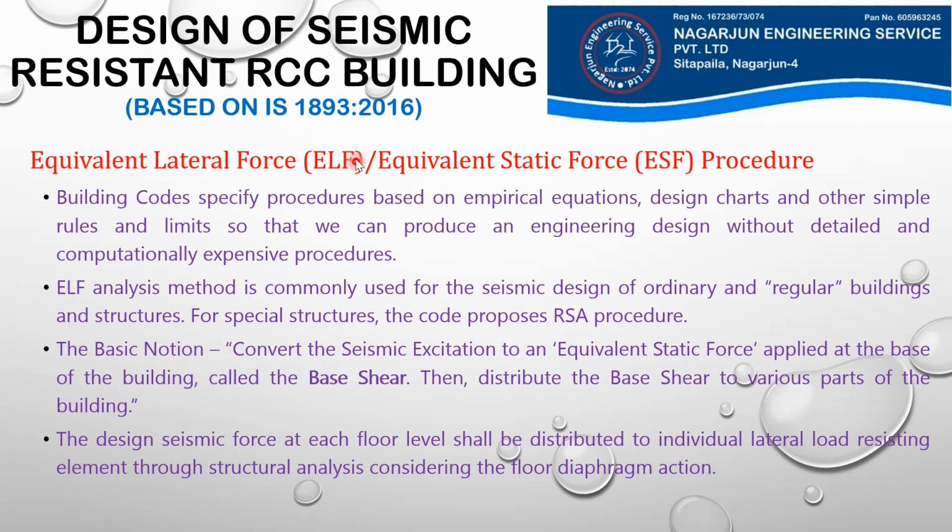So the basic notion of ELF is to convert the seismic excitation, that is, to convert the earthquake forces, to an equivalent static force. That equivalent static force, which represents our earthquake scenario, is then applied at the base of the building, which is known as base shear. Then that base shear is distributed to various levels or various parts of the building. How we will convert that excitation to an equivalent force, and how we will apply that force to different parts of the structure, we will learn in detail when we are designing the structure.